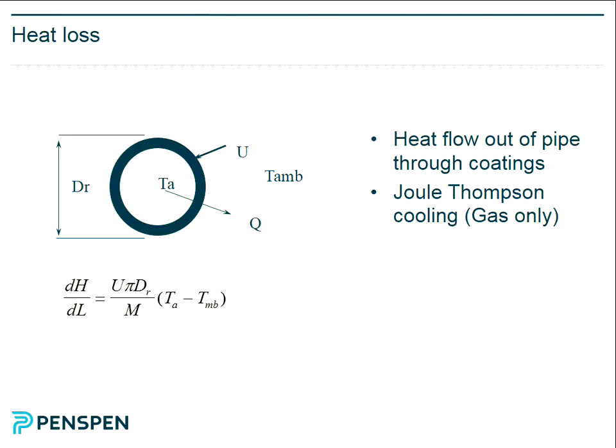On the other hand, if you have a buried pipe which is under 2 meters of silt or sand, you'll find this will be the dominant one, this will be negligible, this will be negligible. So it's knowing what to consider when that is the important thing here. So the overall heat transfer coefficient is 1 over that, is 1 over internal plus 1 over the pipe plus 1 over environment. So these are the special cases: free pipe, pipe in a bundle, semi-buried, buried by a berm, basically. So the pipe and its environment contribute towards the overall heat transfer coefficient, which affects the rate at which heat flows out of the pipe.